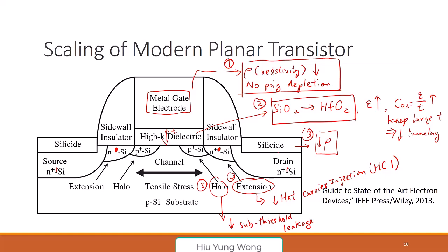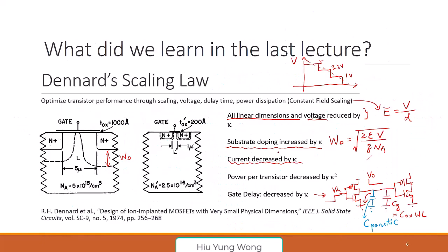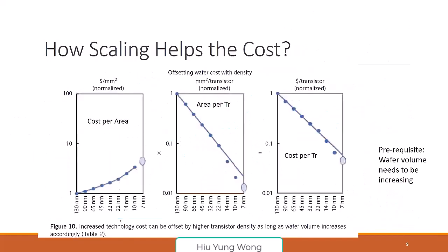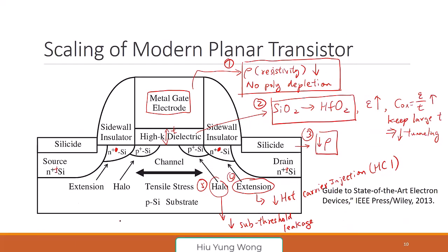But this is very difficult to use in the semiconductor process. Later, we use implantation. That's why you see this Dennard scaling is very interesting. For now, you don't understand why it's so important. But the paper is called Design of Ion-Implanted MOSFET. So you can see that in 1974, ion-implanted MOSFET is something new. Now no one will say I have an ion-implanted MOSFET. Everyone knows that. Unless you say a diffusion-formed MOSFET, then maybe that can be a paper, right? So in 1974, people started doing ion implantation, and then they tried to think about how to scale it, right? Now, sorry, I go too far.